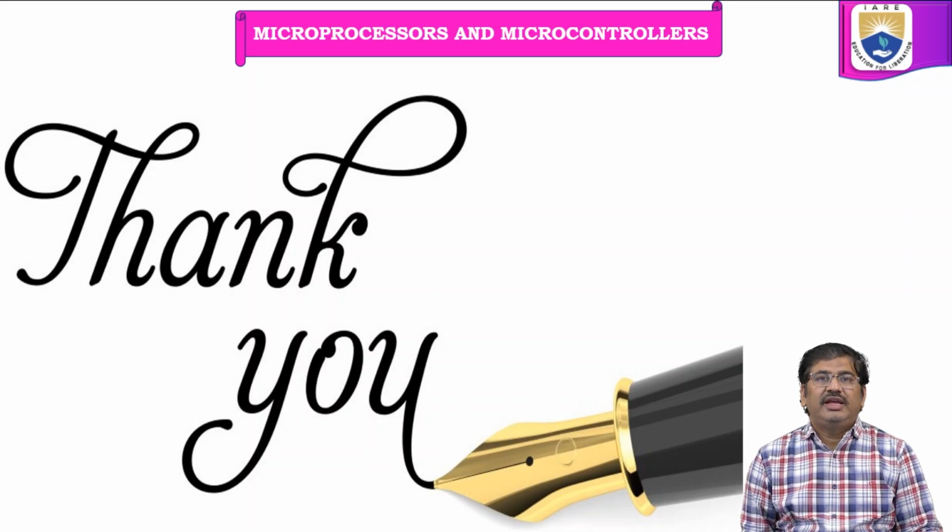Next instruction is LAHF, which is for loading the flag register contents, that is the lower byte, into AH register. SAHF is for storing the AH register contents into the lower byte of the flag register. The next instruction is push F, which is to push the contents of the flag register onto the top of the stack. For every push F operation, the stack pointer will be decremented by 2. Pop F pops the contents of the top of the stack onto the flag register. After every pop F instruction, the stack pointer will be incremented by 2.